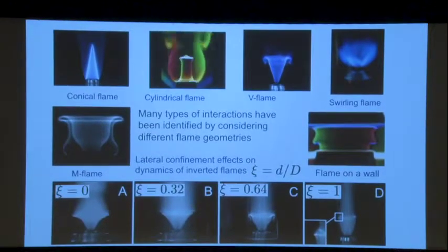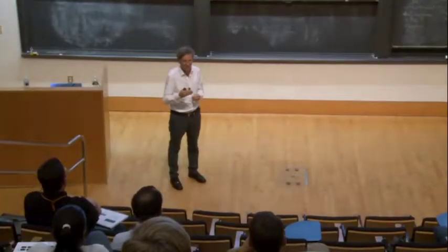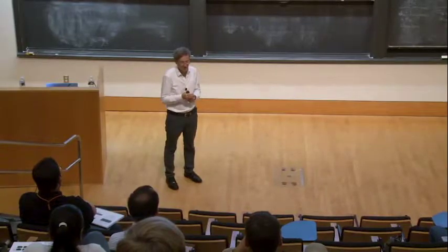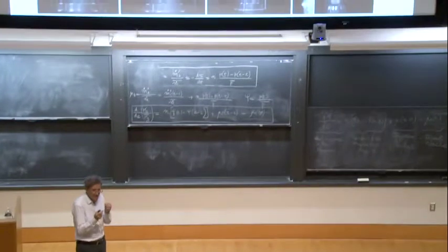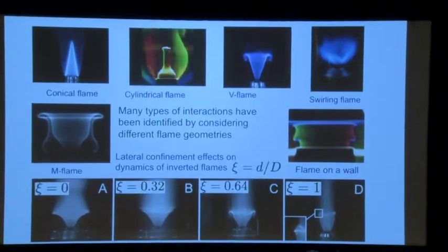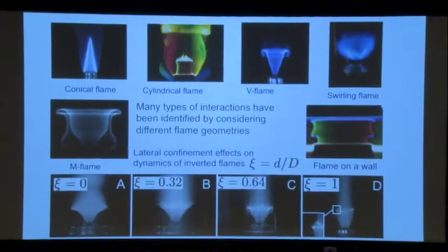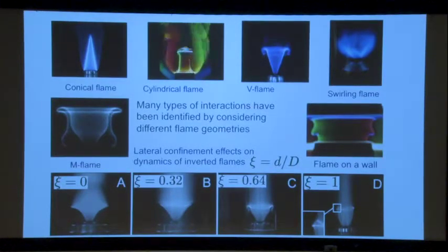You see the flame is collapsing, and actually, as the curvature gets larger, very highly curved flames have an effect on the burning velocity. And this effect is through the Markstein length or Markstein number. And this experiment here was used to actually measure that effect, because you have a flame which becomes like a cylinder, and you can actually have very high curvature as it collapses.